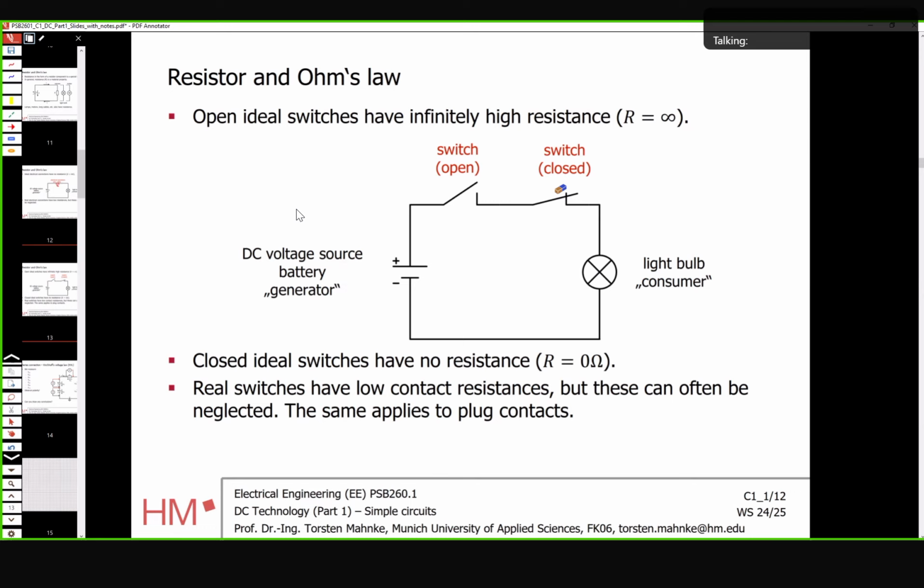You push the fuse into metal clamps. On the metal contacts between fuse and clamps, there was so much corrosion that it was a very high resistance at this point. All the voltage that came from the battery dropped here, and there was no voltage left for the starter, the lights and the instruments. That's the reason why everything became dark.